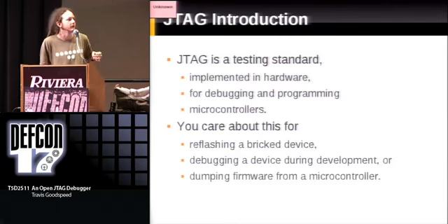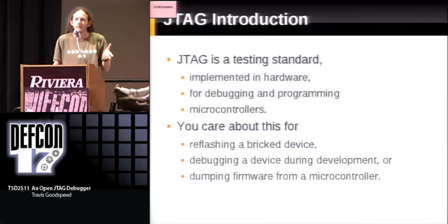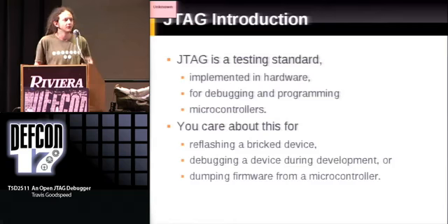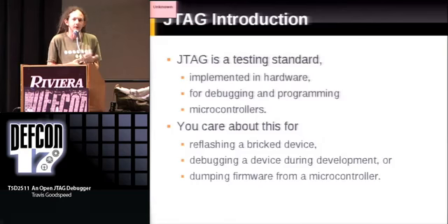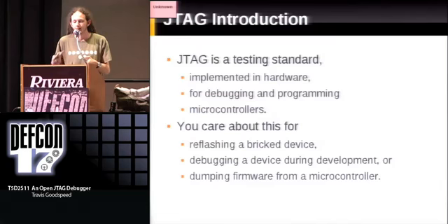So while in software, recompiling takes a couple of minutes or a couple of hours for an extraordinarily large operating system, in the case of hardware, you're looking at a turnaround time of months between deciding that you made a mistake and actually getting to try the next iteration of your design. So you need some sort of debugging, both to verify that what you intended to put into the design was fabricated correctly in hardware, and to determine that the software that you're running works properly.